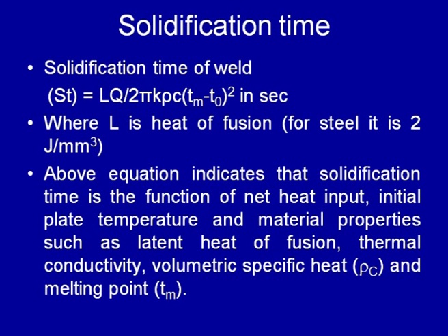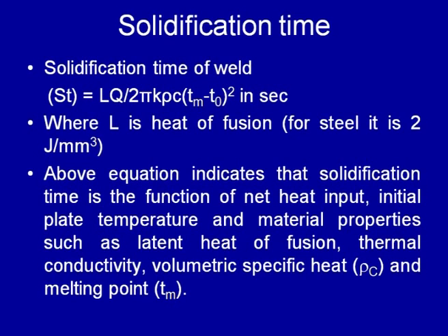Further, an increase in thermal conductivity and an increase in specific heat will increase the rate of heat extraction, and so the solidification time will decrease. So, the above equation suggests that solidification time is a function of the heat input, the initial plate temperature, and the material properties such as the latent heat of fusion, thermal conductivity, volumetric specific heat, and the melting point.